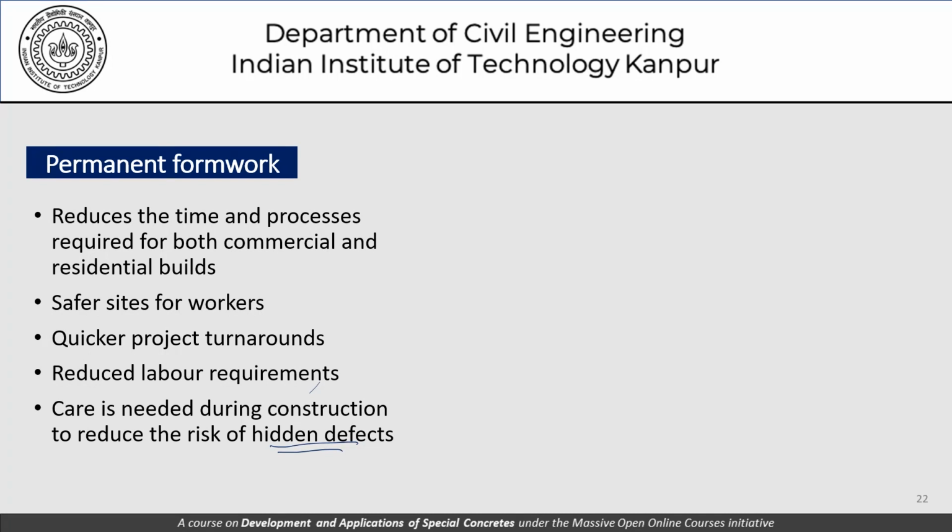So here we are talking of a situation or a construction method where the entire member is not precast. In a precast construction, the entire member would be precast. In this construction, part of the formwork, or that part which becomes the part of the structure as a formwork, is precast or is manufactured somewhere else, brought to site, and in situ construction happens as usual. The in situ placing of concrete, setting of concrete, and so on happens as usual.